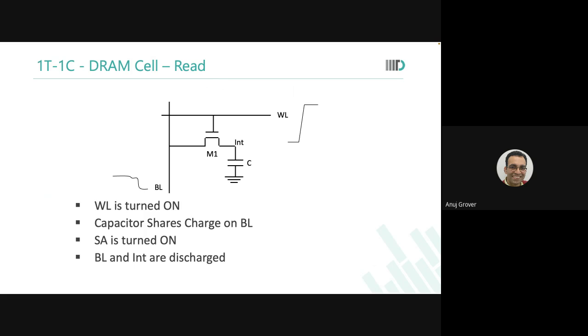Are you able to see this? In SRAMs, when you have to do read and write, this is called read modify write, then you first do a full read operation, you turn on the sense amplifier, then you do a full write operation because the write driver is needed. In DRAMs, read modify write is the default read.